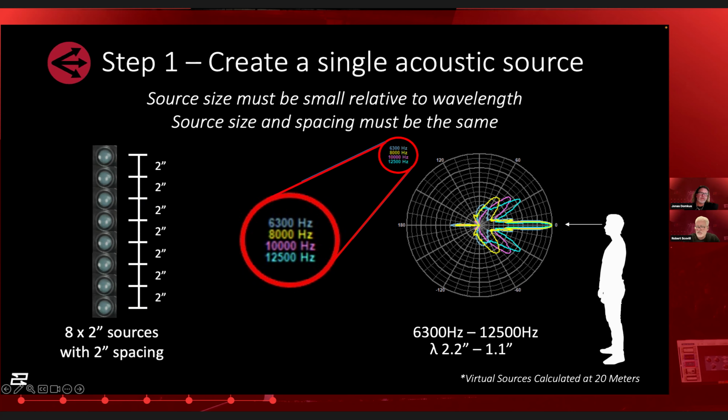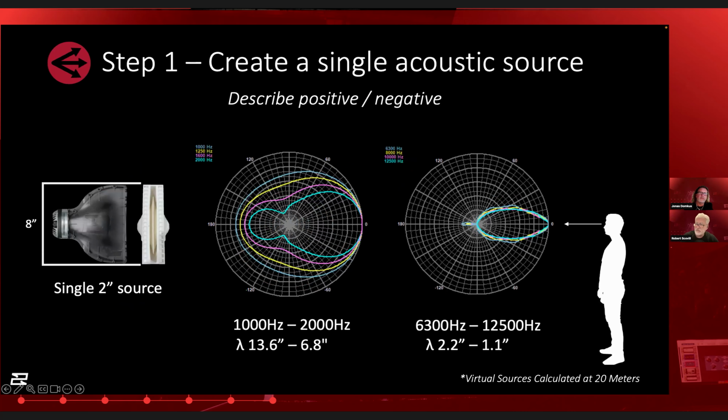So this was the challenge with line source in its early days. Well, what do we do? How do we attack this and clean this all up? And of course, the idea was to put the high frequency element on a horn and use an isophasic waveguide and regain control of that high frequency, right? So that's what we did. You guys are all aware of what's happening in isophasic these days, I'm sure. So here's a 2-inch driver on an isophasic waveguide, and voila, look what happens here. We get a very controlled and very narrow output, right?